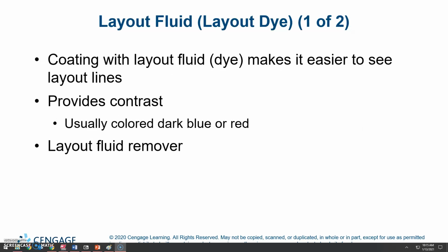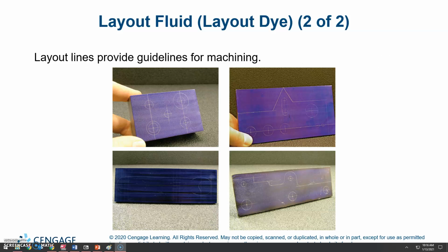Layout fluid. Coating with layout fluid dye makes it easier to see layout lines. It provides contrast, usually colored dark blue or red, and there is also layout fluid remover. So layout lines provide guidelines for machining.